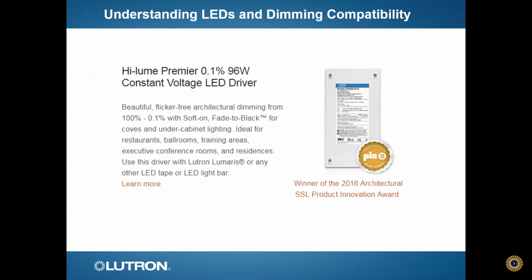So just know that if you're looking at tape lights or under cabinet lights, things like that, if you're having issues dimming the driver that they've got, you might have the option of swapping it out for a Lutron driver. These drivers you can purchase through AllNet. It's not something that they would have stocked on the shelf. They can custom order it. It is a stock item at Lutron, so it would ship out quickly. But I just wanted you to know that is an option.